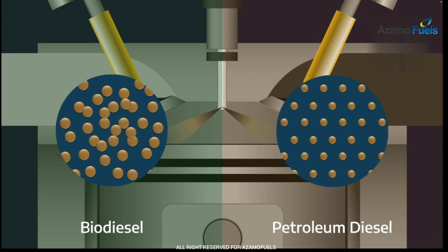And soot obviously leads to increases in oil viscosity because of the loading of solids. And it can also start to wear the engine components as well, because when soot agglomerates, it becomes abrasive. So that's another negative consequence of the use of biodiesels in engines.